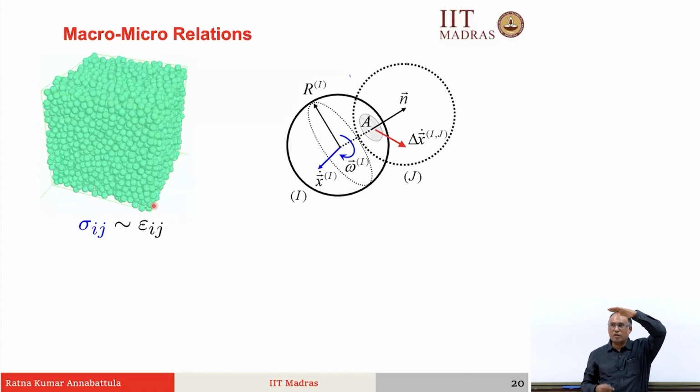Let us say it is a displacement controlled experiment, that means you are pushing the piston, then you can calculate strain. Can you or can you not? Because you know the initial size of the assembly, and by moving the piston you know the displacement, and the displacement by the initial size is your strain. In each direction you can compute, so you can actually compute the strain tensor, not only a strain component in a particular direction.